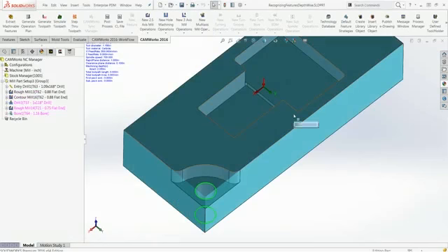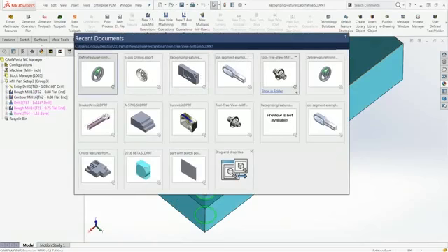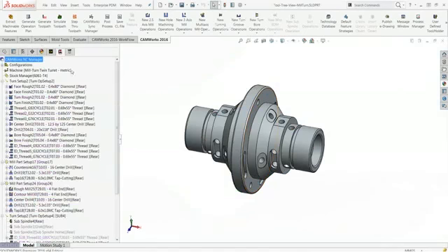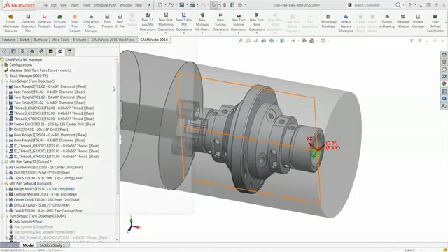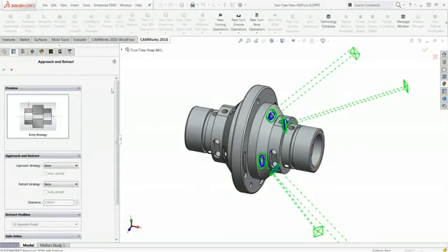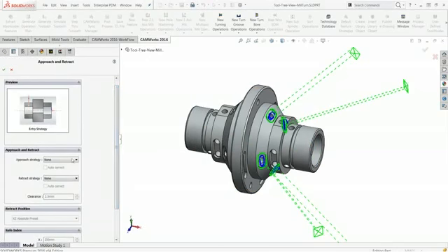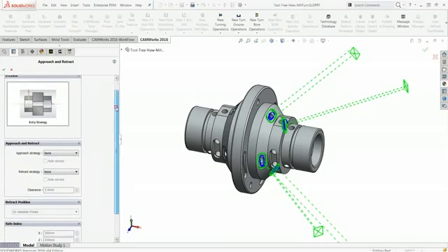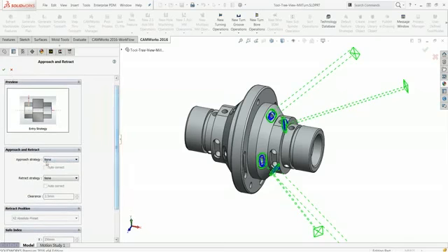Another feature that I will show you is just in our mill turn options. So in our toolpaths within mill turn, if I just edit one of these toolpaths, under my NC tab, we now have an advanced approach and retract settings. If I turn that on and press the define button, I'll open up the little preview window here, and you can actually see the different approach and retract settings that are inside of here. If I change them around, you can see it move in the preview and show you what you're actually setting. So Z and then X.